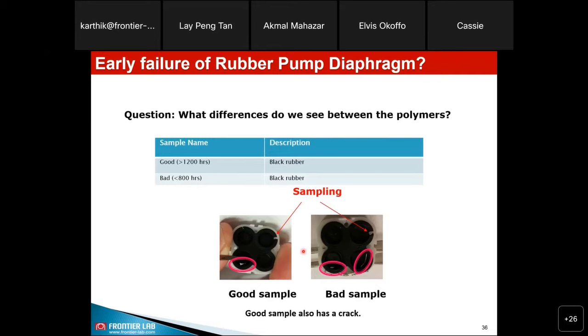All this can generally be determined by using this double shot technique. The first step is thermal desorption, followed by flash pyrolysis for the polymer. This is what I have shown as one of the major applications in rubber and tire industries.